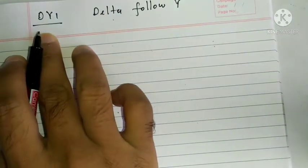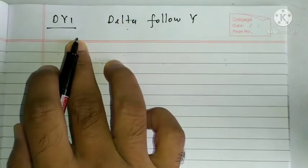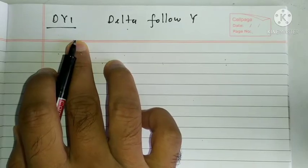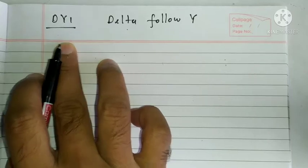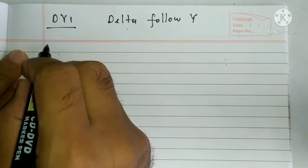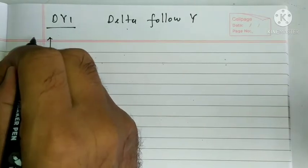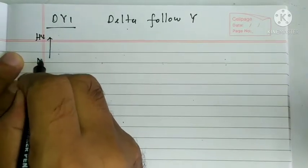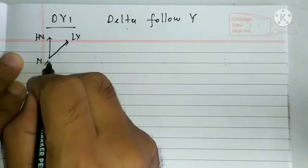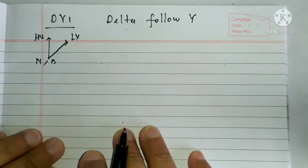That means in this case the LV winding will be drawn first, and based on LV we will find the locus of all arms, A arm, B arm, C arm, and based on that we will go for the HV winding. And what is LV to neutral? HV to neutral is here, and LV to neutral is at 1 o'clock, right?